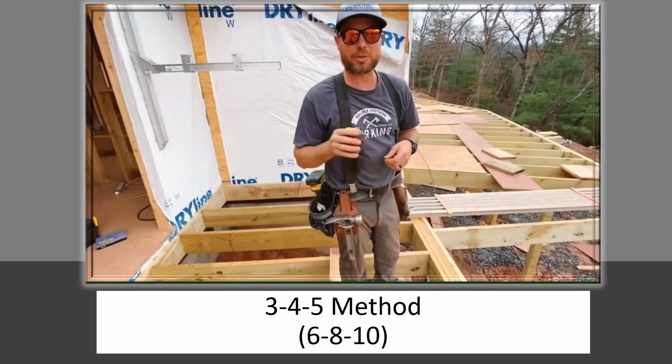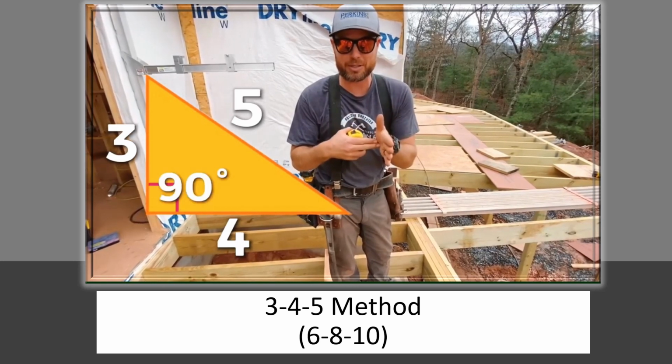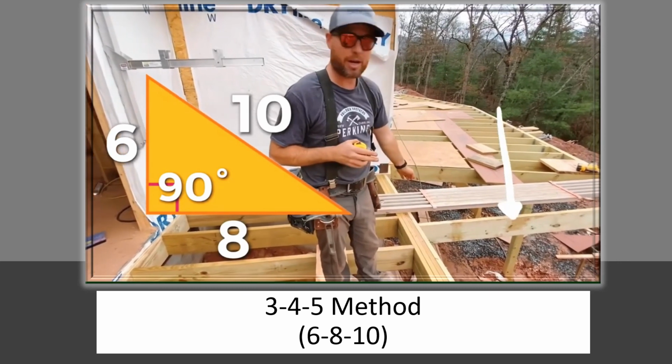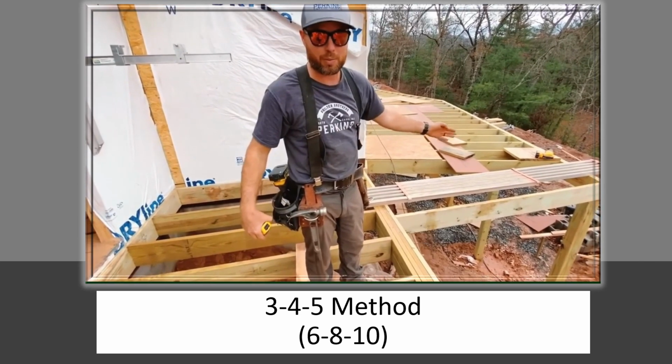I'm going to show you one of the greatest carpentry tricks of all time. And that's using a 3-4-5 triangle to figure out if a corner is 90 degrees, okay? And what we're going to do, though, is double that. We're going to do a 6-8-10 triangle. We're going to figure out if this board right here is running off of our other band at 90 degrees, which is what we want, okay?